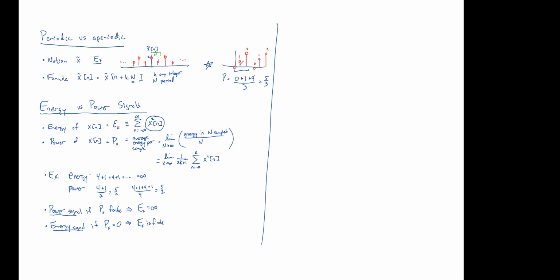Okay, I see that. And the reason for that intuitively is that you think of it as a voltage signal across a 1 ohm resistor. So you've got a 1 volt pulse here and you've got a 2 volt pulse here. Your 1 volt pulse will cause 1 amp of current to flow, which gives you a power of 1 watt. Your 2 volt signal will create 2 amps of current, which will create a power of 4 watts. So when we talk about the power or energy of a signal, we're always squaring the actual signal value.